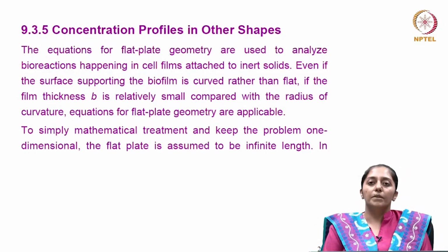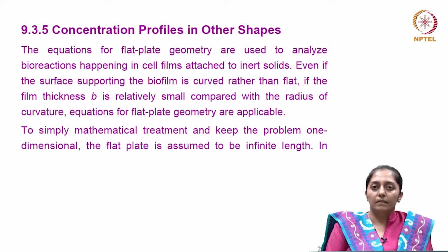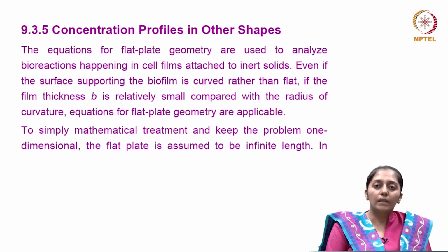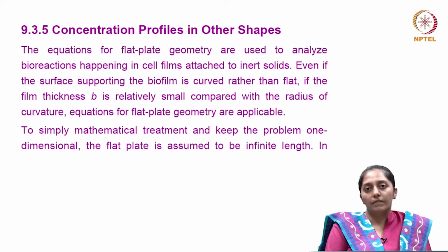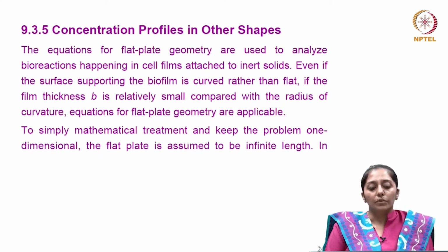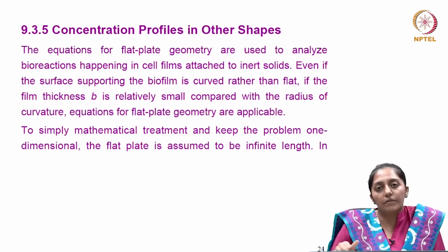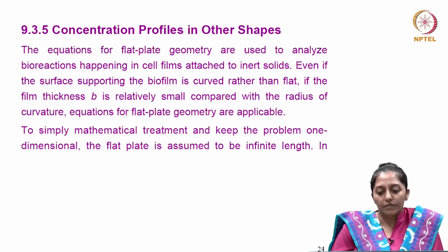Now, we have been assuming from the beginning, for ease, the particle shape as a spherical particle. Now, let us see how the concentration profile will change with other shapes which we come across in various bioprocesses, like biofilms, where the geometry will be like a flat plate. The equations for a flat plate geometry will be used to analyze the bioreactions happening in cell films attached to inert solid surfaces.